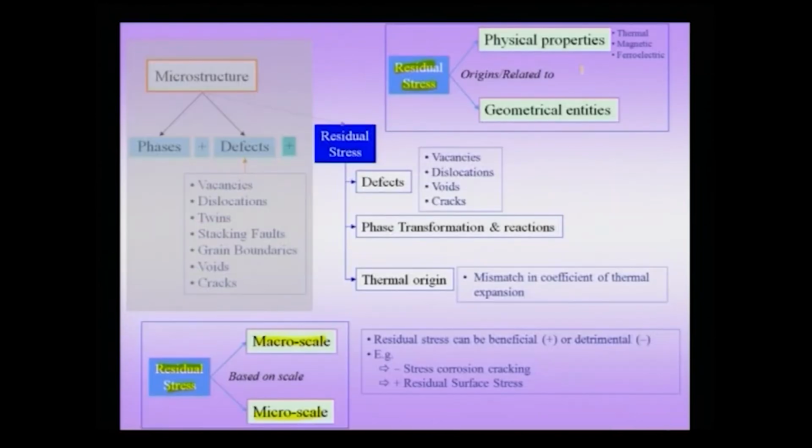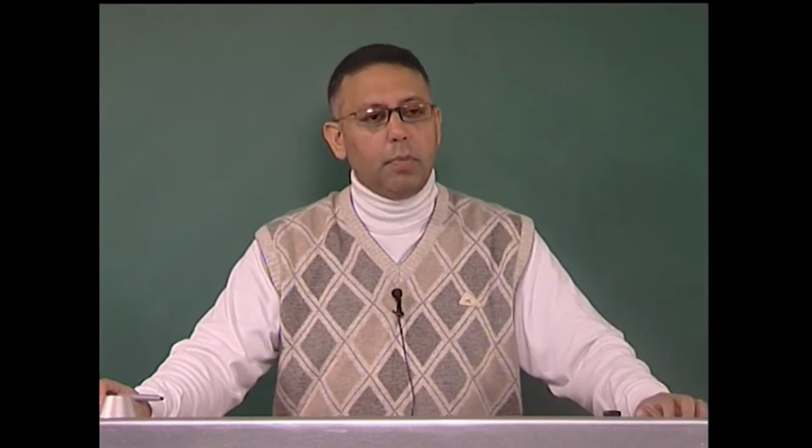Now, why is it that we need to classify residual stresses? We need to understand that there are multiple origins of residual stresses, some of which can be at the very small nanometer length scales, some of them can be at the length scale of the entire component. Some of them are related to the processes which are occurring in the material like phase transformations and reactions, while others are related to the differential thermal cooling which the sample feels.